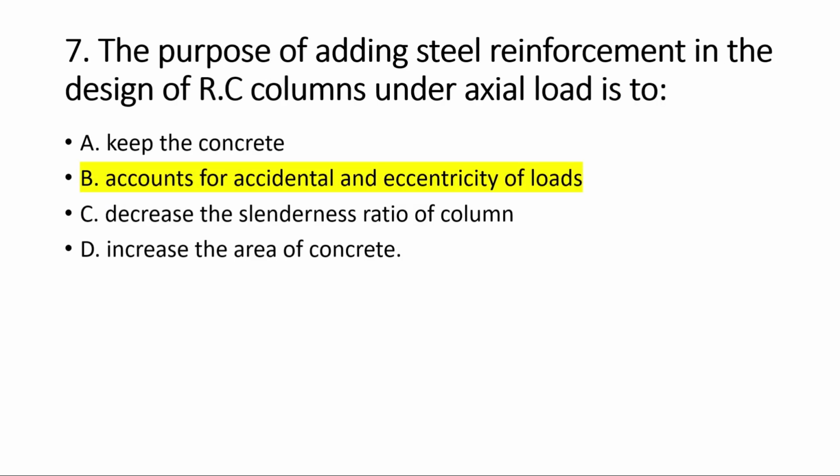The purpose of adding steel reinforcement in the design of RC columns under axial load is to account for accidental loads and eccentricity of loads. Okay, so we know it is to account for accidental loads and eccentricity of loads as per Indian Standard 456:2000.